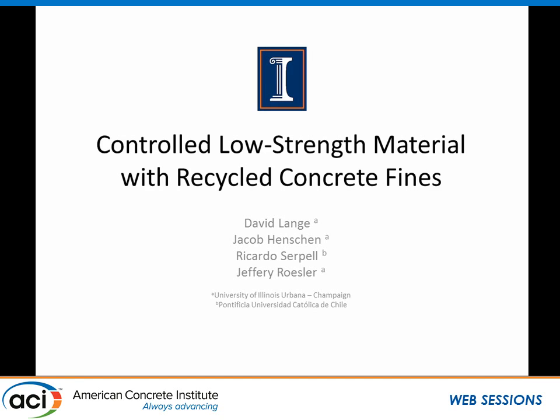If you're just making traditional concrete materials, you can go back to Abrams' law and count on it to work and so forth. But when you're using recycled materials, probably the biggest challenge is that you don't really know exactly how these things are supposed to interplay. And that's why both Michael's presentation and our presentation are utilizing these kinds of statistical experimental methods to explore the interactions. Okay, so let's go ahead and take a look at this.